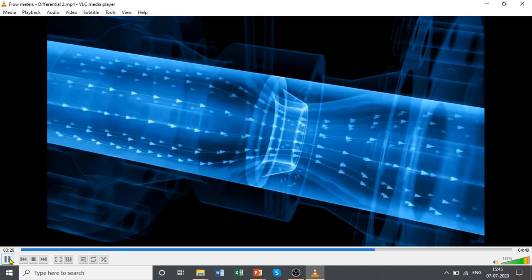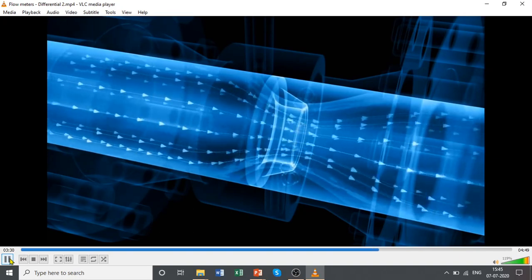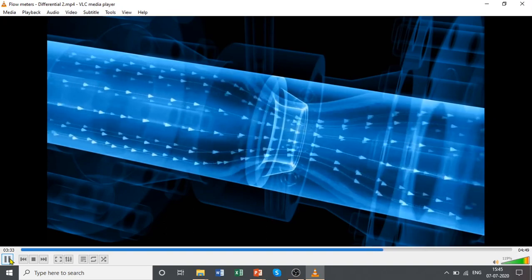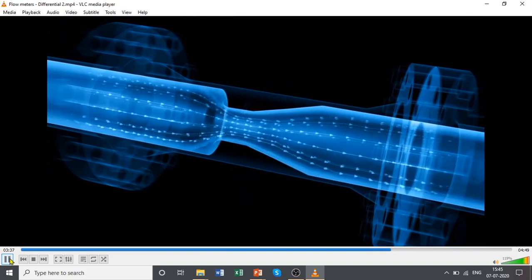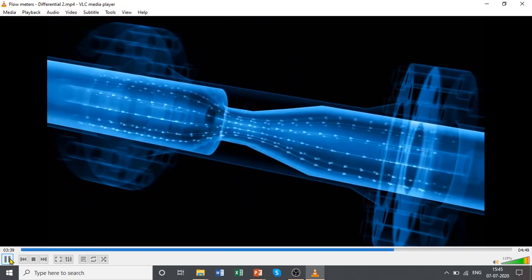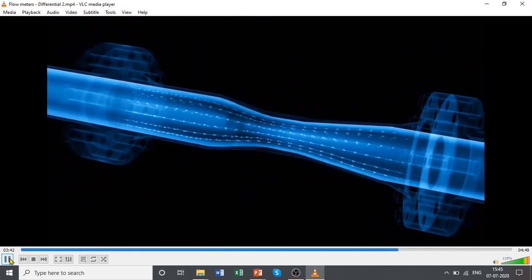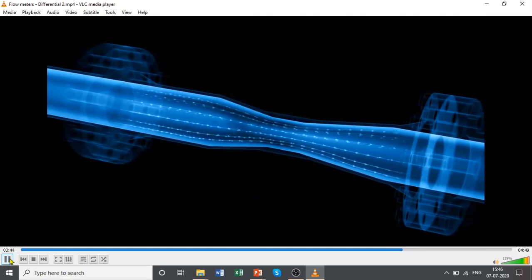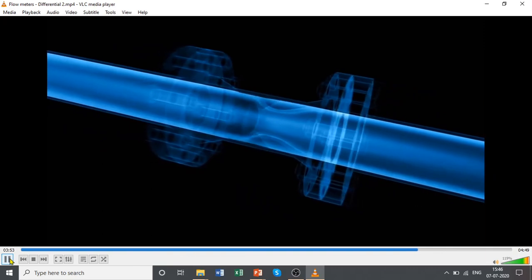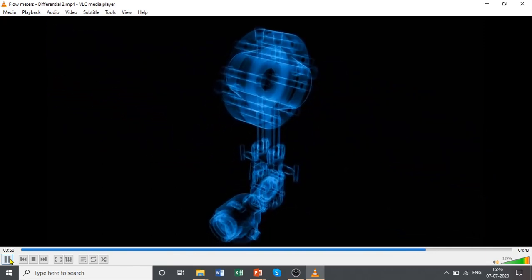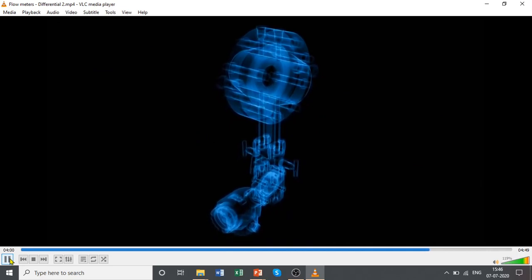Nozzles are particularly suitable to higher flow velocities or to fluids with abrasive solid particles. Turbulence reduction is even greater with Venturi nozzles. And finally with Venturi tubes, where the restriction is created by longer conical constrictions in the pipe wall. All these designs can be supplied with different restriction diameter sizes, so that the pressure loss and the differential pressure generated can be optimized for the process conditions.